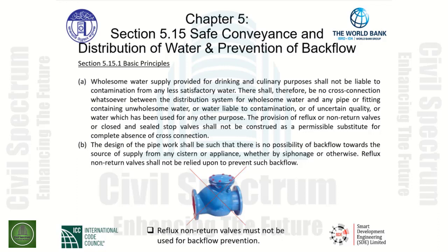Right there is a requirement that is mandated that wholesome water needs to be supplied for these functions within our buildings. There shall therefore be no cross-connection whatsoever between the distribution system for wholesome water and any pipe or fitting